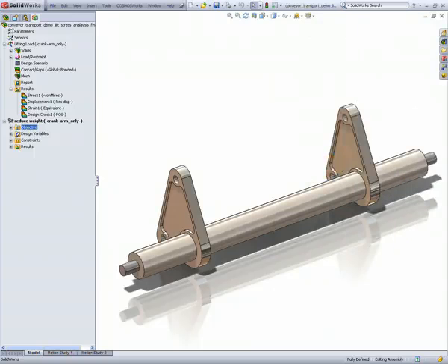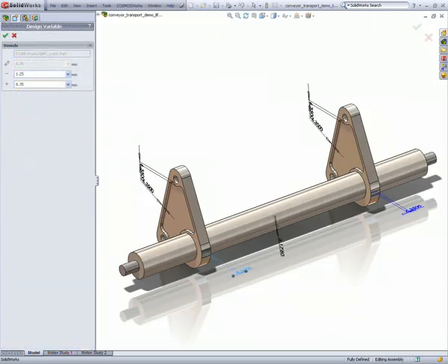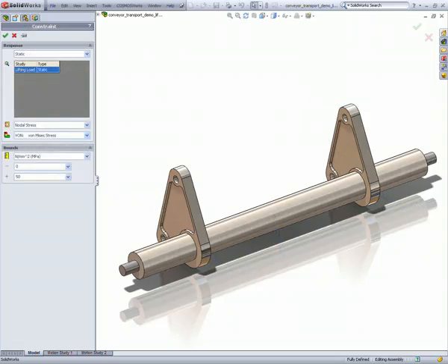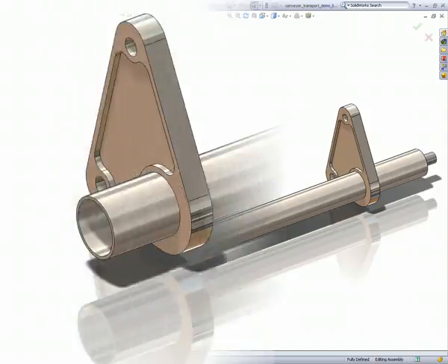Now that we understand the working loads, optimization couldn't be easier. Being part of the SolidWorks environment makes geometry changes child's play. All the designer has to do is pick what features he would like to change and a dimensional range over which they can vary. In this case, we let SolidWorks vary the web, flange, and hole offset thickness, as well as the torsional tube's wall thickness. We also set a constraint that stress must remain below 50 megapascals.